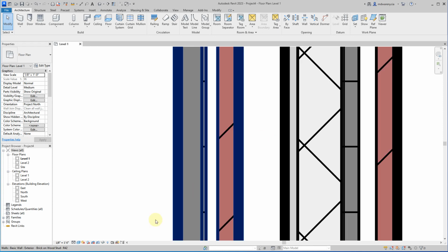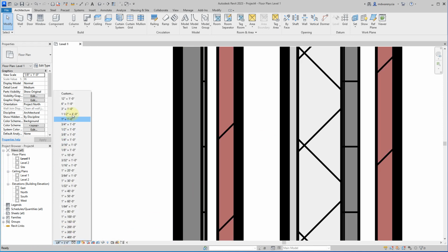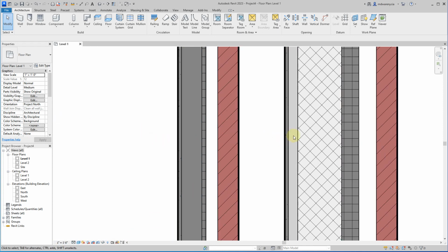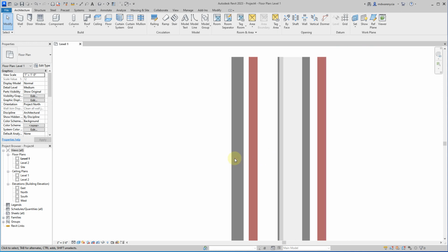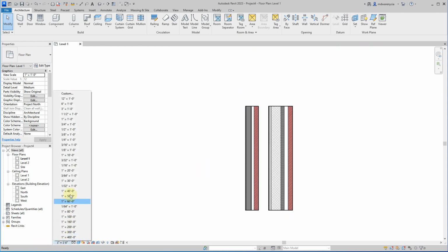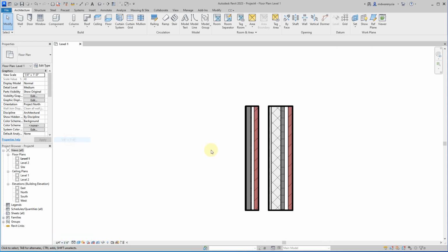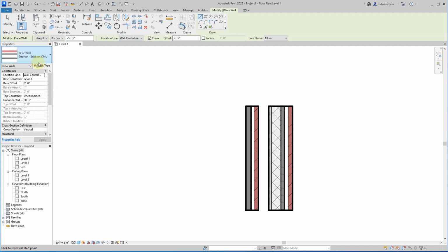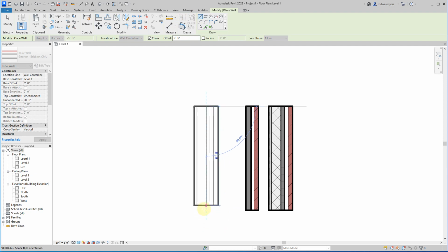And then we also got rid of this furring right here that was that extra wood that allowed the actual gypsum wallboard to be attached here. So we have two very different thicknesses of walls here because we made those changes. So when you're working with Revit, the thickness of your walls is going to be very important. So let's go make another wall type now, and I'll just draw it right here.